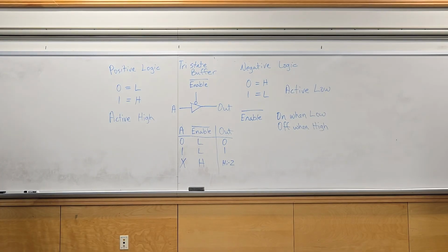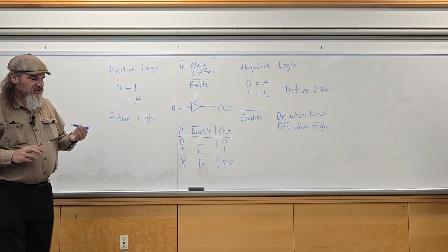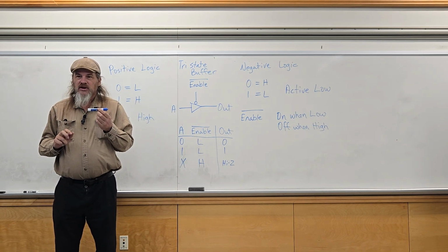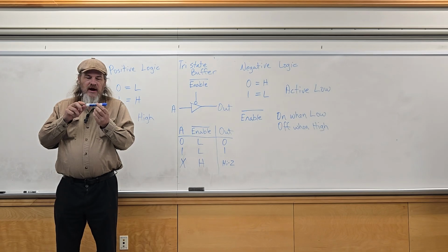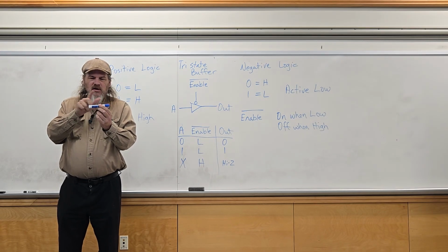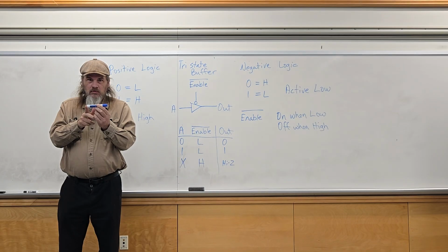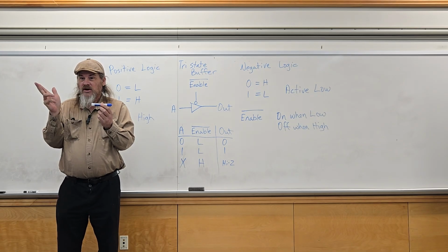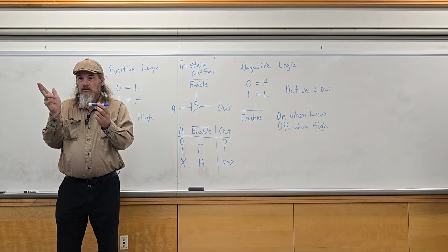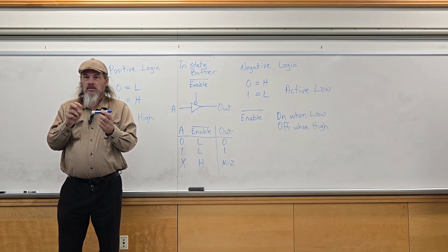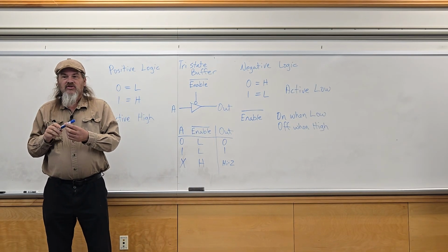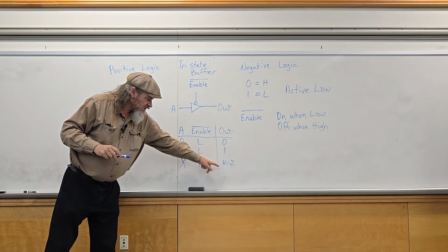What that basically means is, say this is a battery. All the gates that we've been looking at so far, you have high over here, low over here. What's the third possible condition? No connection at all. Neither high nor low. It's like the wire isn't connected to the battery at all. So that is the high impedance state.